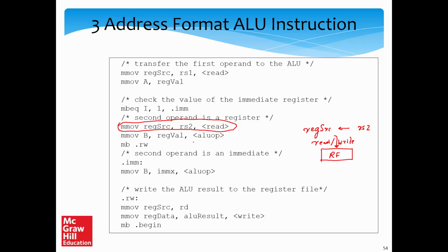So we'll need to have a very small forwarding circuit. But that's a very simple detail. I'm ignoring that. But pretty much the reg source micro register needs to be accessed. We need to get its current contents. If its current contents are being modified, that's okay. Whatever we are writing, we can sort of bypass the value. That's all right. And then we can start the access. So in this case, we save one cycle. So this is an interesting, neat, elegant, efficient optimization to make.